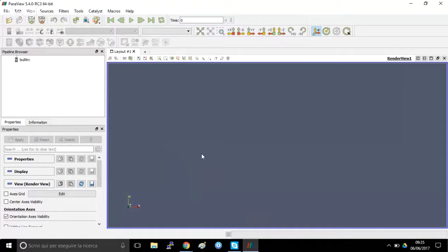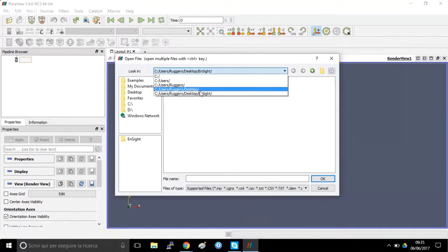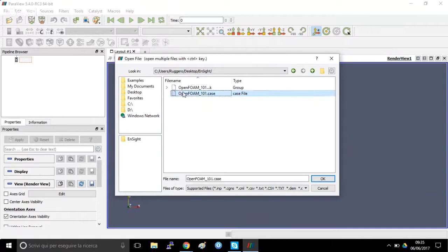Hello everyone. Today we are gonna see how you can integrate pressure and flow through a surface. At the same time, we're gonna plot a small pressure over distance graph. As usual, we have already downloaded the file from CONSELF and we open the inside folder, inside of which we can find the openfoam.case file.